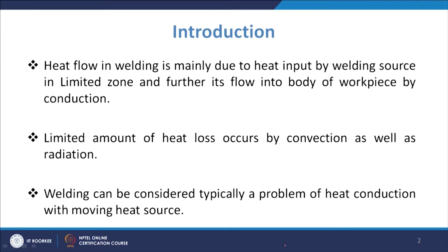Certainly we know that we are using a heat source. That heat source will generate heat, and that heat is generated in a local manner. It does its job by melting, but the heat then flows into the body, because all around the zone where the metal is melted you have the metallic material. So that takes the heat from it, and that goes by conduction.